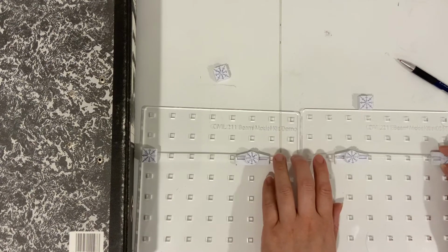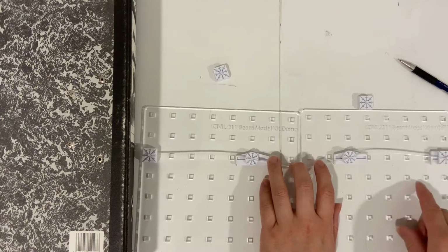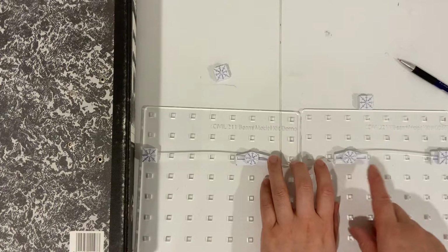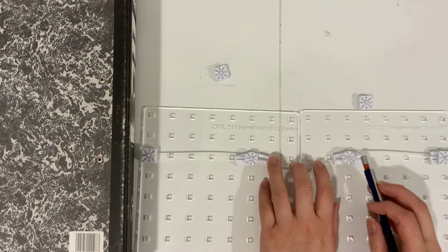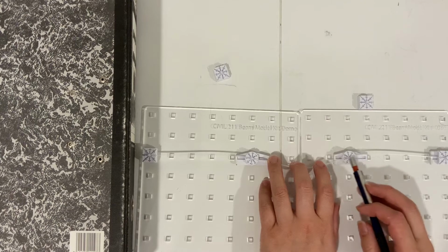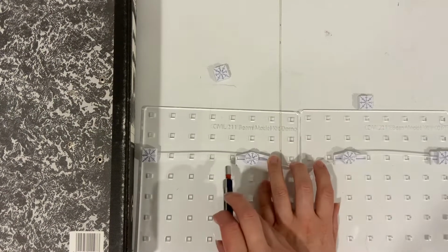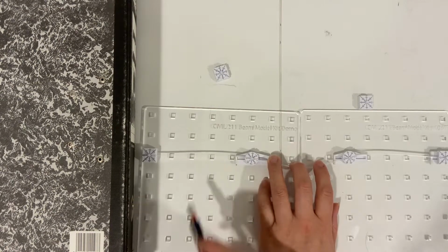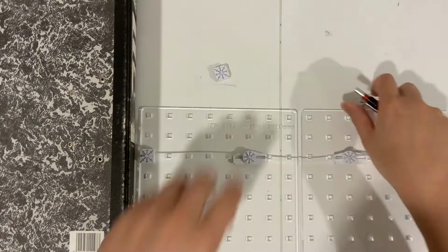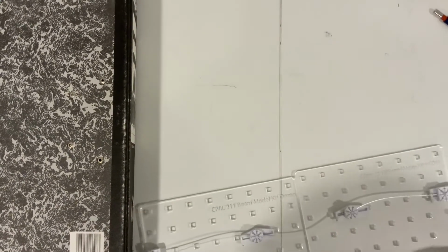So let's apply. I'll pretend we apply the load there as a UDL, and you can see the deformed shape. So you'll be able to see that this one here is hogging. This is hogging down here, and this would be hogging down here. Okay. So let's see how that would work out in the sketch.